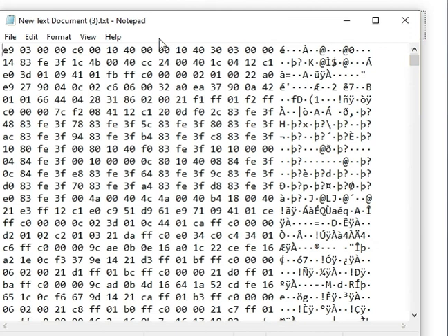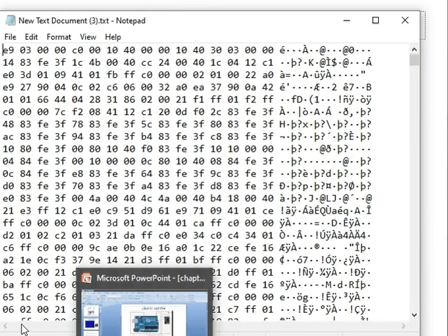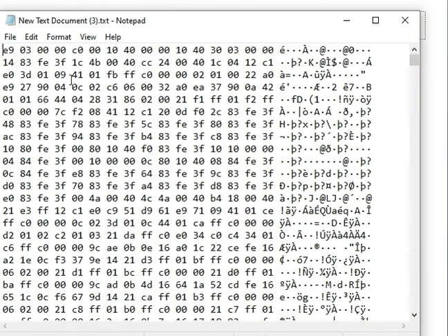So this is just for verifying whether your device is in good condition. You can always have a firmware dumped in it, and you can test whether the AT commands are working or not. Okay, so these are a few things which you can try if you are free enough, or if you have an ESP8266 module and Arduino, you can try out this experiment.